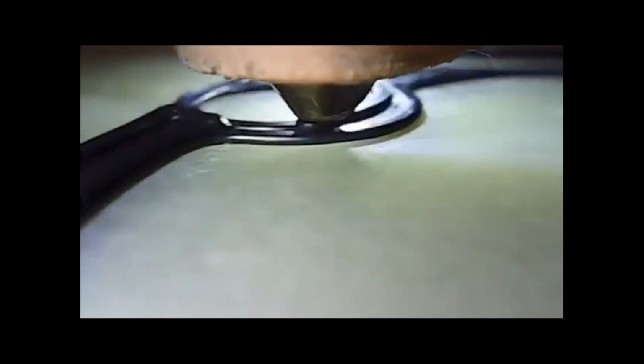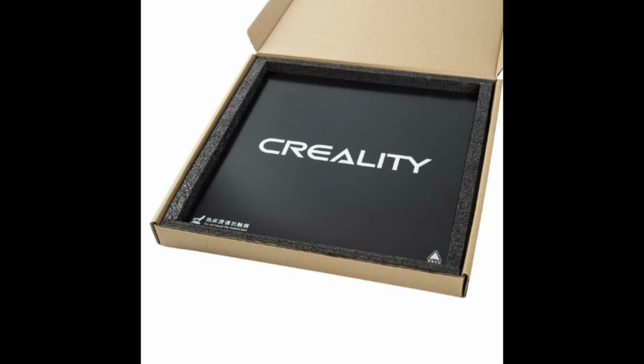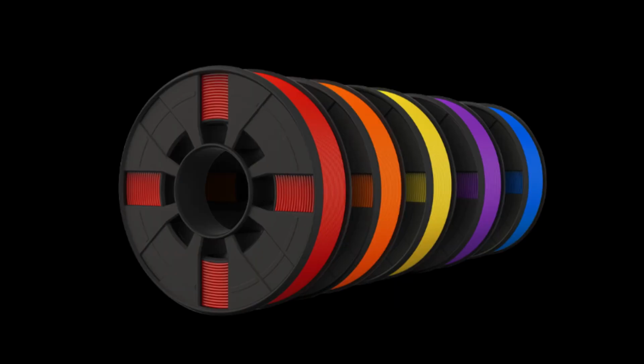The added weight on the X gantry from the Microswiss direct drive also causes the X gantry to sink on one end. And so, to solve this problem, I used a dual Z-axis system. The dual Z-axis kit allows me to put two stepper motors instead of just one to lift the X gantry up along its path. Another thing I bought for my 3D printer was a glass bed. Glass beds are very flat, which is very nice for 3D printing. Especially with flat materials, you're able to have a more consistent bed level.